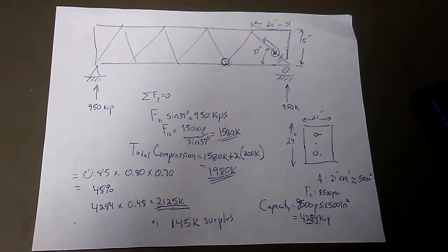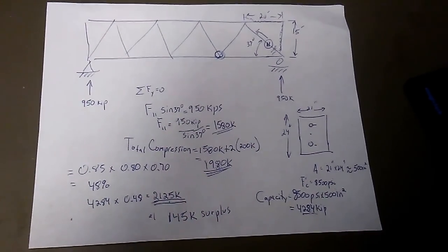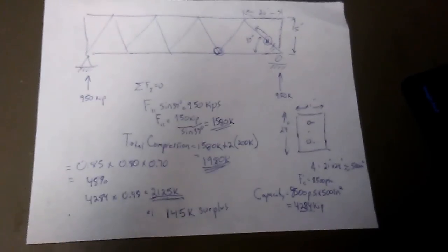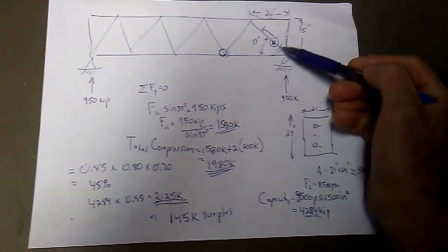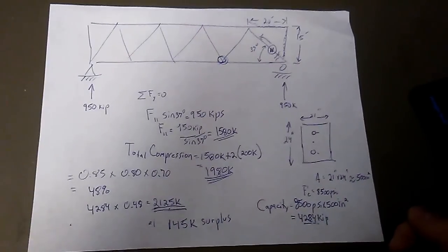Yeah, we don't like the cracks. We have to figure out why they were there, maybe when they occurred. But we don't really need to worry about them because if they're in this compression member, they're not going to grow. All right, so these are my conclusions.